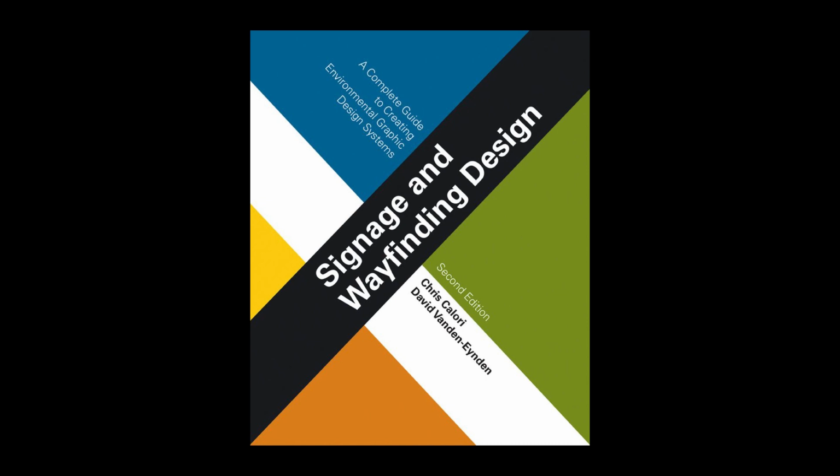While this is a relatively easy process if the architectural drawings were created in CAD, some clients may not want to take the time. If the plans are from a pre-CAD era, just be happy that the drawings exist at all, and take them however you can get them, making sure to check that they reflect the currently configured plan. Whether the plans are clean or not, they should be grayed back so that they're still readily visible but faded into the background relative to the sign locations and numbers, which are not grayed back.